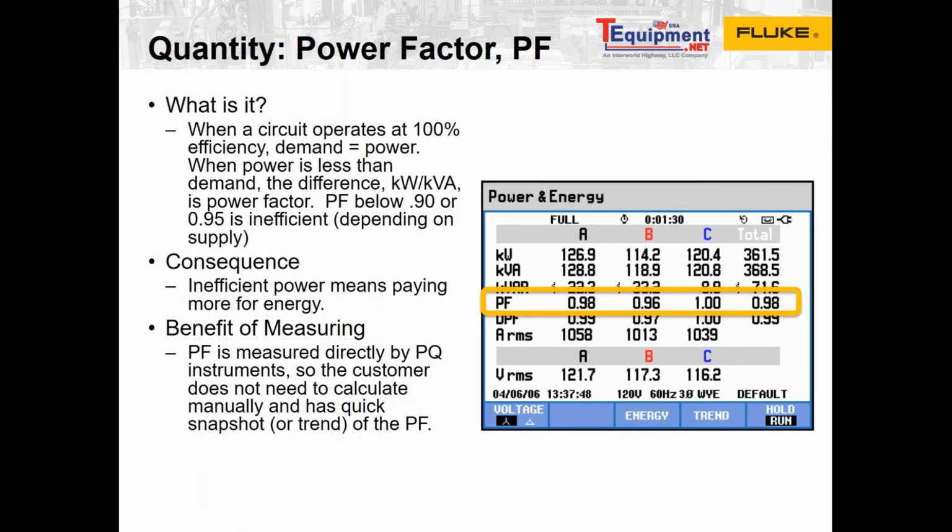You get that additional fee for your entire billing period. So it doesn't even matter if you only had poor power factor that was less than 0.95 for 15 minutes. You get charged for whatever that billing period is, usually month to month or on a 3-month basis, which can really suck. So consequently, these larger facilities will want to ensure their power factor stays above the 0.95 threshold.